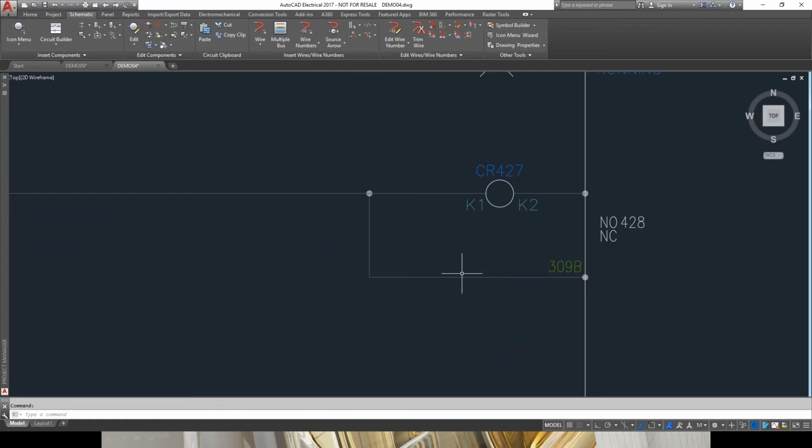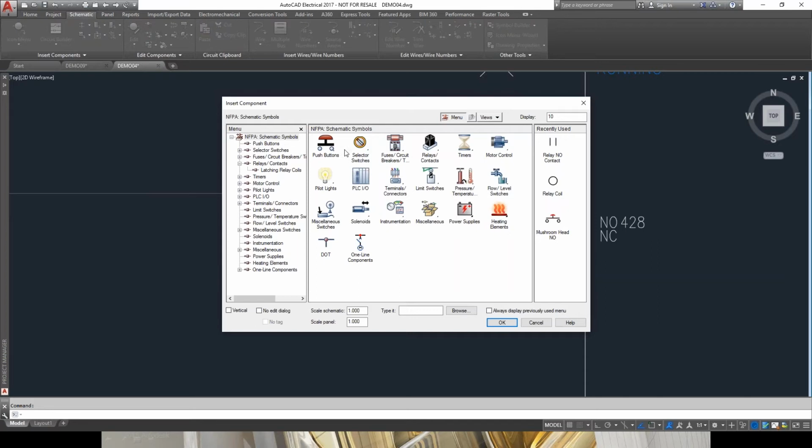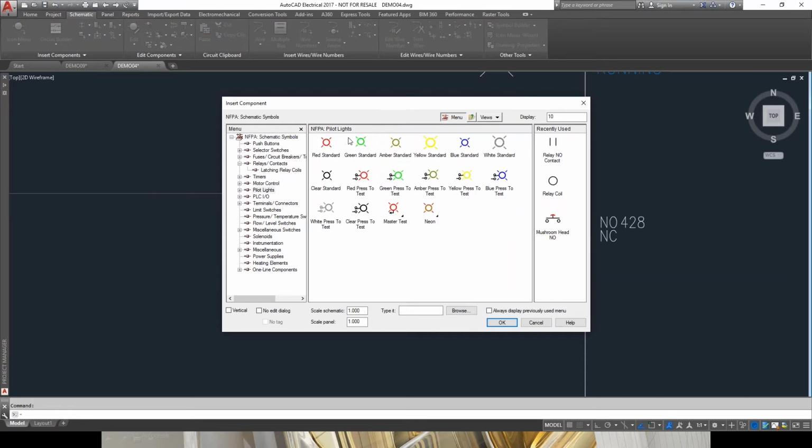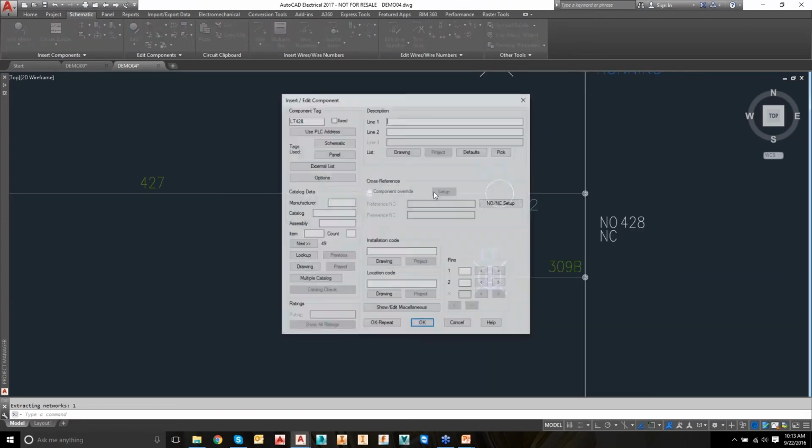So the simplest way to do that, right-click on the component and just select Delete Component. One of the beautiful things I love about AutoCAD Electrical is it will go in here and heal all that for you. It deletes the component, heals the wires back together, fixes it all very quickly and easily. There's no stretch line to deal with, anything like that that you might be doing inside of base AutoCAD right now.